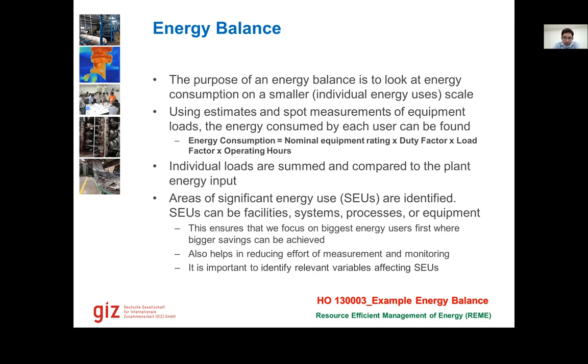Obviously, another way is to do the measurements. If we can do a spot measurement, let's talk about electricity. We say a certain motor is usually running at 4 kilowatt load. But is this motor always running, or does the load vary? So we also need to identify that load factor. Then we need to see if this machine runs 24 hours every day, or does it also have stoppages like changeovers or maintenance? So we estimate that duty factor as well. And then how many overall hours of operation do we have in a year? We multiply those together and we can estimate energy consumption.